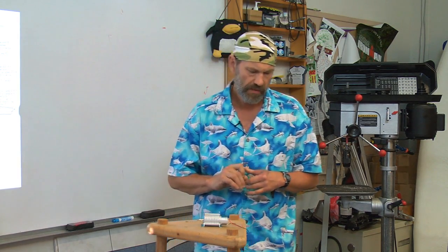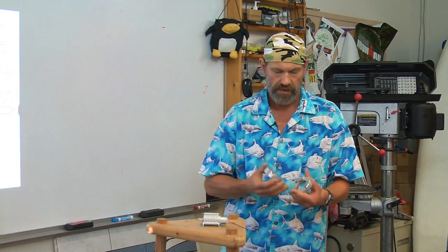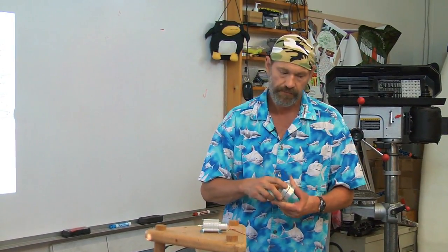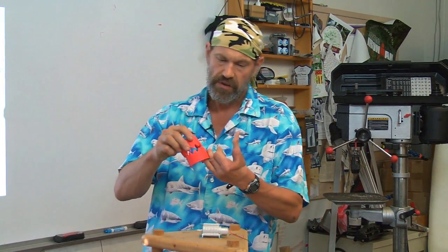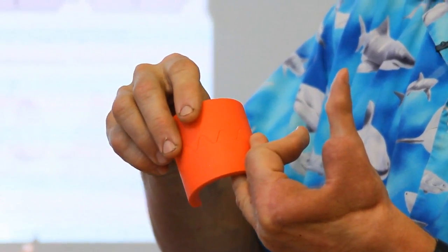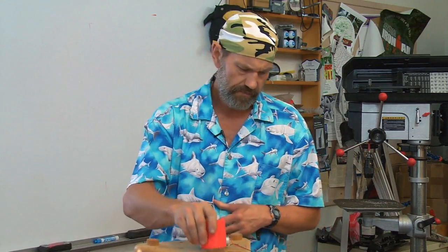Elastic averaging. Recall from topic 3 that we talked about kinematic systems and elastically averaged systems. Now we want to go into a little more detail on elastically averaged systems with respect to coupling design. We showed the kinematic systems earlier, for example, the three-tooth systems. And one of the last areas we talked about was elastic deformation of these objects. By going to a lot of teeth, you have more of an averaging effect, so the error in any one tooth is not felt so much because you have a lot of teeth.